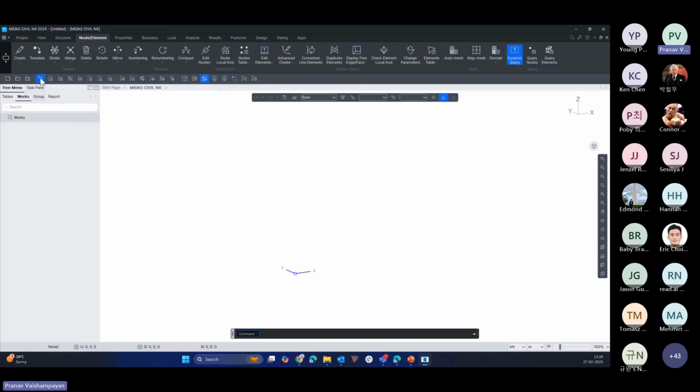The fourth option from the left-hand side will be frequently used. You can just hover over those options and identify what each option represents. Then there are activate all, active only, and inactive options, which are again frequently used. Then there is a cubic option. If you hover over it, it says hidden. It will help you toggle between the 3D view, rendered view, the line element view, and the node element view of the geometry.